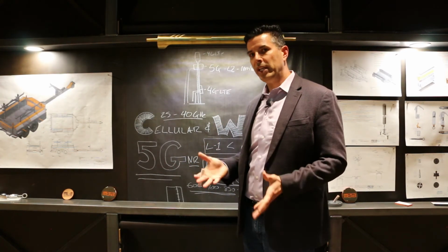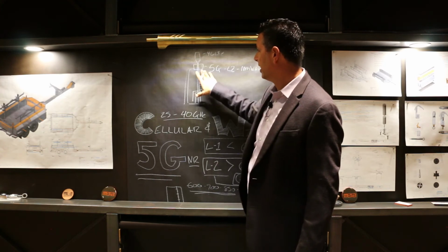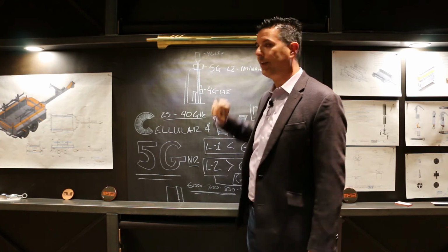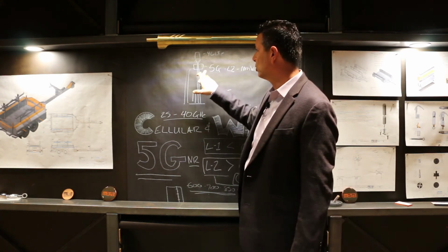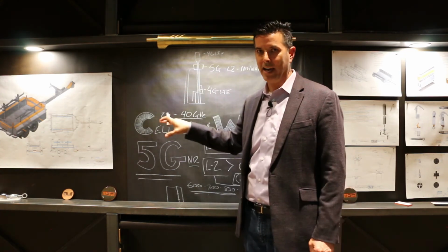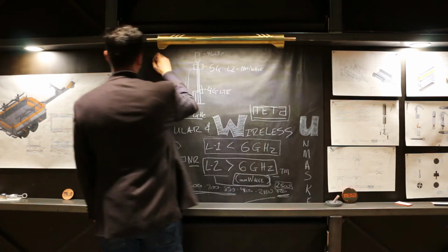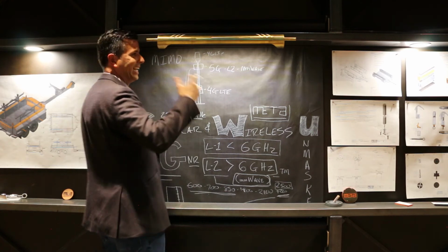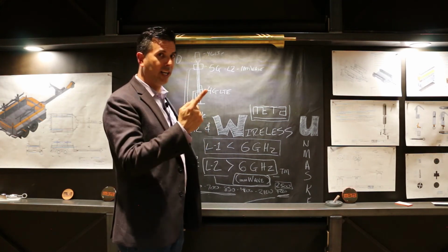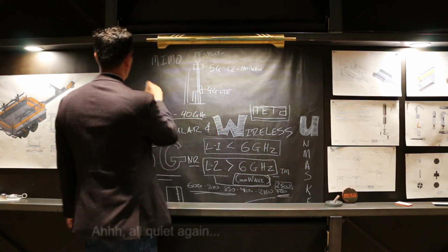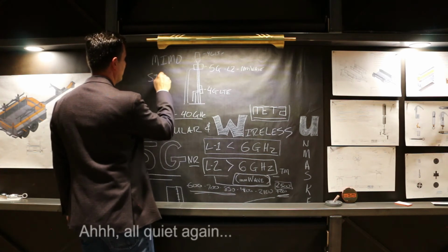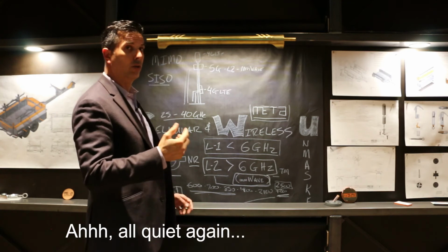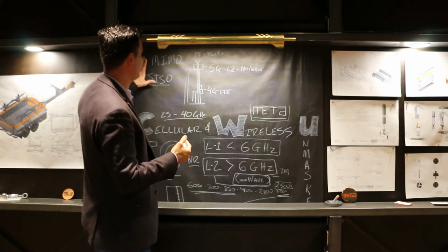One of the other reasons why the antenna and the radio are one unit for your L2 millimeter wave 5G is they use a technology called massive MIMO. MIMO, in simplest terms, just means multiple in, multiple out. Anytime you have more than one antenna element. That would be SISO if it were one antenna element, single in, single out. That's not uncommon to have SISO. You don't get as good throughput with SISO as you do with MIMO.